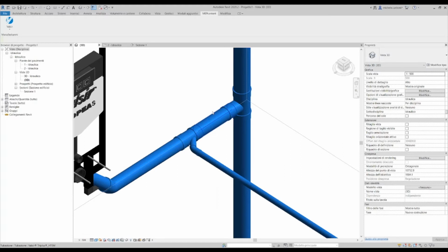For the realization of the transition between the horizontal pipe and the vertical down pipe, we are now using a 90 degrees T-branch. This could be a better solution with respect to the previous one, because we can decrease the velocity of the flow that is entering inside our wastewater system. Again, decreasing the velocity means that we can decrease the vibration, and we can decrease the sound, the noise level inside our system.